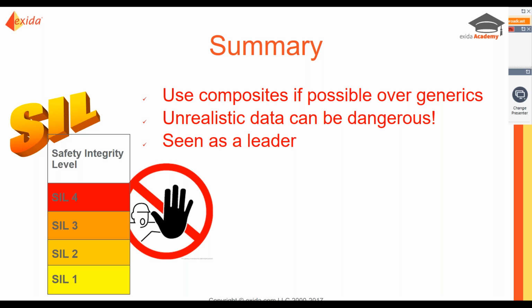And at the same time, if you get unrealistic data, don't just simply use it. Raise a red flag. It can be dangerous in some situations. And if you are doing those type of things, using SIL certified devices, being realistic with your failure rates, you're really going to be seen as a market leader.